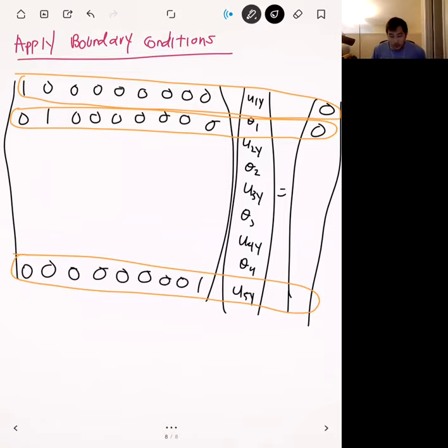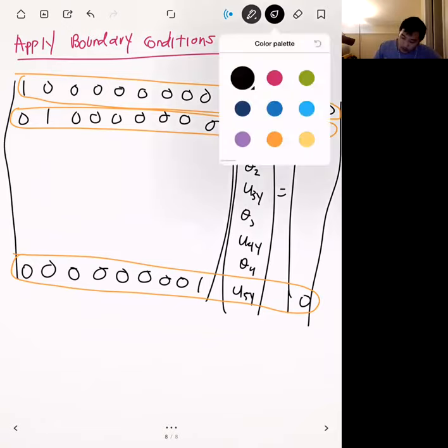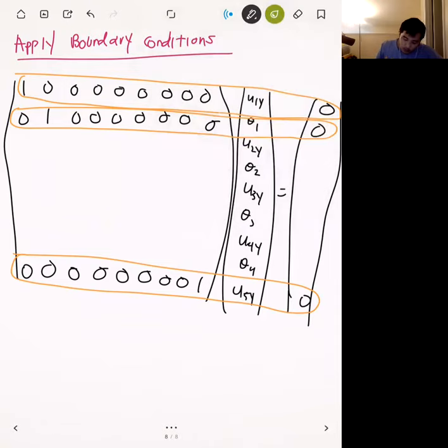Right. And so that's what you would do for the fixed supports, right? And so remember, you would affect the fixed supports by changing the entire row to zeros, and then change the diagonal entry to just 1, okay? And then also for the load acting on node 4, right?